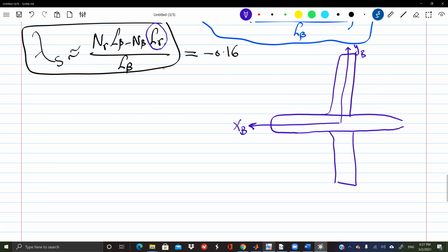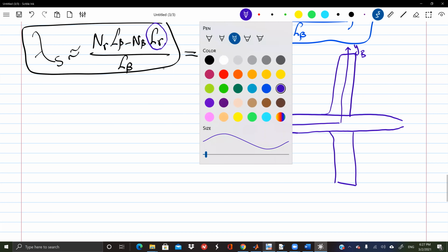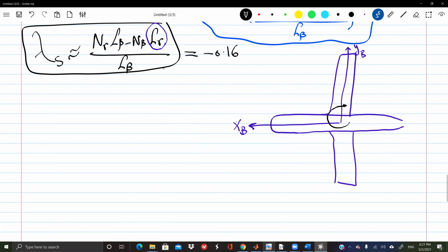And let's get the effect due to the wing. So first of all, let's apply this R. This is my positive R, yaw rate. And let's see the effect on the wing. Well, the right wing will go backward. The left wing will go forward. So if I have a station here that is distance y from the center, it will go backward by how much velocity? Can you tell me? RY. Very good. Not minus RY? RY, and this will go forward by RY, right?